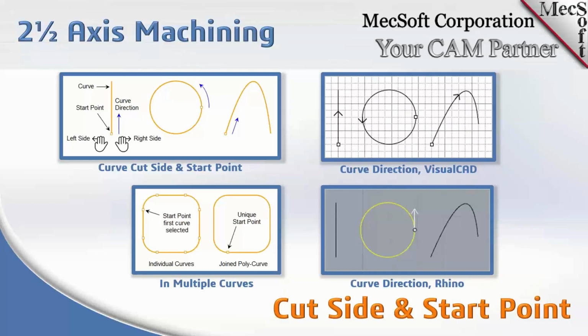A quick note: this slide applies mostly to the profiling machining operation, because the curve direction and the right side and left side come into play only in profiling. As we mentioned, in facing and pocketing, the closed curve determines the side, because in pocketing it's always on the inside, and in facing it's always on the perimeter. So we're really talking about the profiling machining operation here. It's important to know. Thanks, Joe. An open NURBS curve is the same: you have a start point and you have a right and a left.